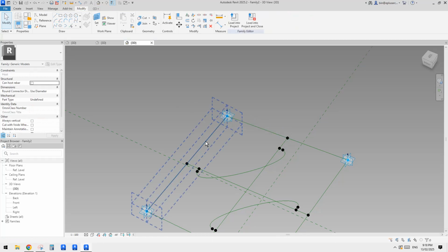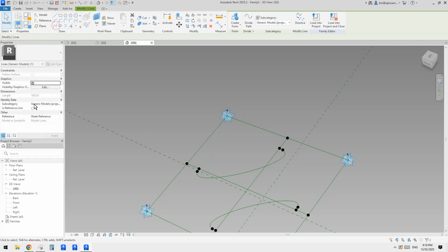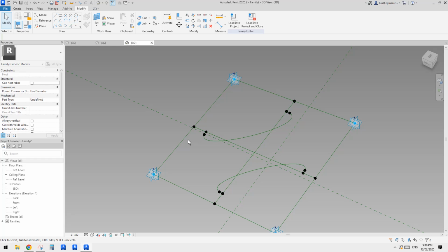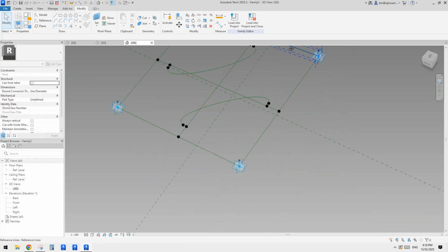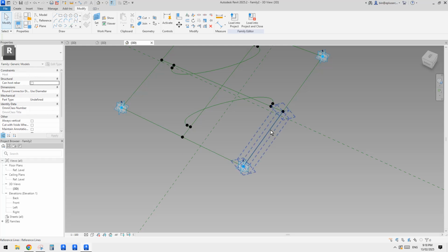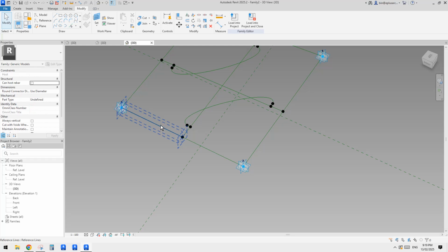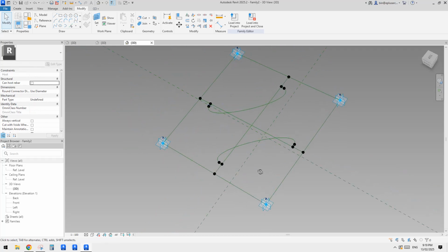And do we have this? No. So you can always use tab and try to pick the half reference line. So if there's none, we just need to create them, right? This one's not a reference line, just need to tick the box. Yeah, this one's there. Okay, good.